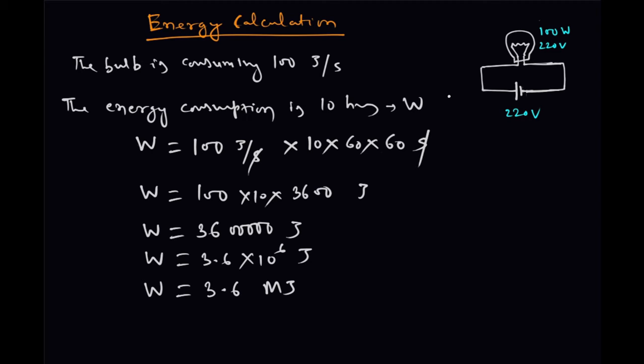So in the household you can see many bulbs and heaters and geysers, there may be air conditioners. Those are high power consuming items. One electric heater may consume 1000 watt or 1500 watt, and one air conditioner may consume 1500 watt or 2000 watt. Their consumption will be an even larger figure.